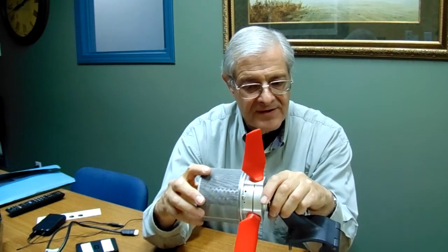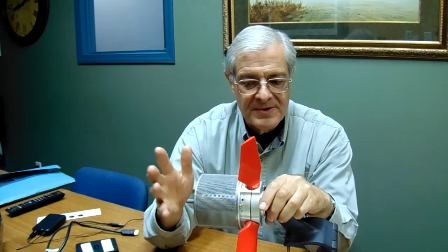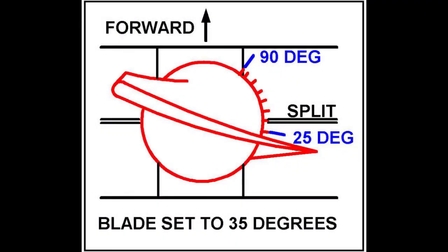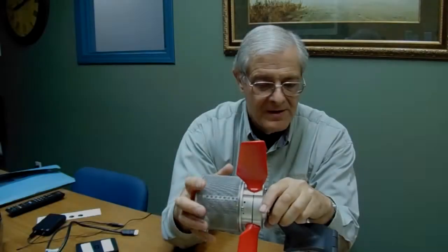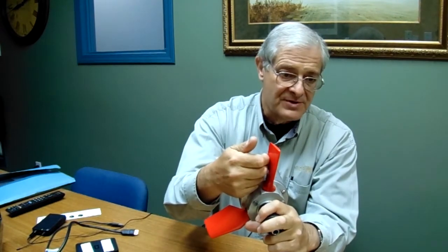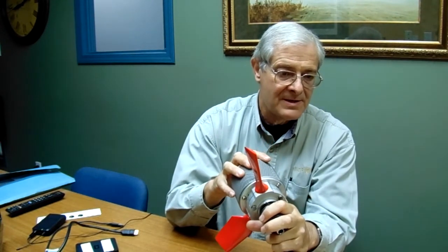With this AU5000 atomizer, the speed of rotation is determined by the angle of the fan blades and also by the forward speed of the aircraft. So if the fan blade is near enough in the feathered position, the atomizer will be turning slowly.